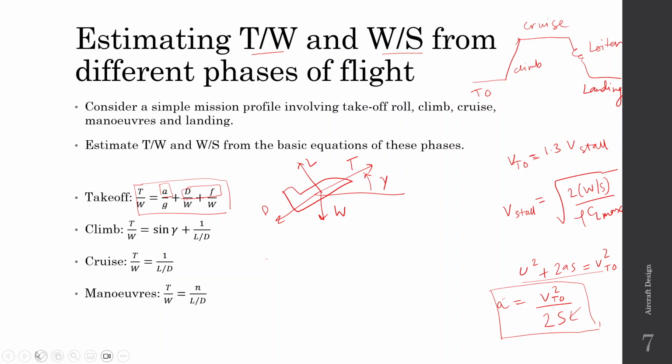So if I only consider the thrust axis, then okay, so this is the equation along the thrust axis. Now if I consider that the aircraft is in a stable climb, so not accelerating, then the right hand side is 0, and then we can rearrange the equation and divide by the weight to get.